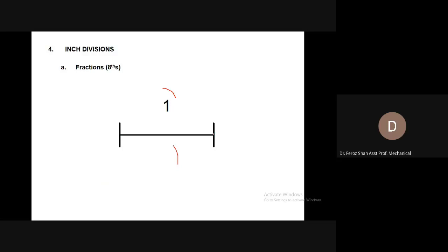This as a center. Now, keeping the same opening of the compass, now this be the center. Draw another two arcs, cutting the already drawn arcs at this point. Now join the intersection points. Now this is not a very straight line because I am drawing it freehand. You will be drawing it with the help of the compass and a ruler.